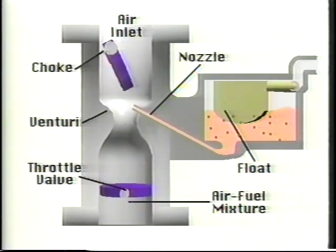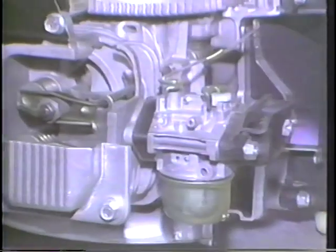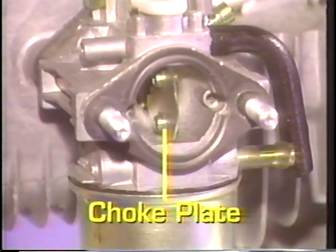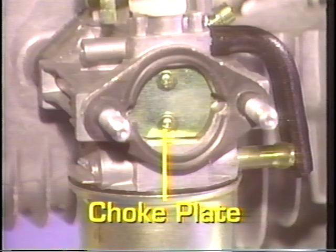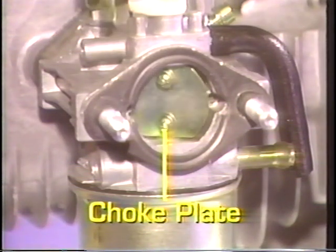The choke at the inlet of the carburetor can be closed to aid cold engine starting by richening the mixture. The throttle can be opened and closed to regulate the engine's speed and power. The carburetor throttle lever and choke lever are connected to the operator's hand controls. Here you can see the choke at the inlet of a carburetor. When it is closed, the engine is starved for air. More vacuum is produced at the nozzle and more fuel is pulled into the engine to support combustion when parts are cold.